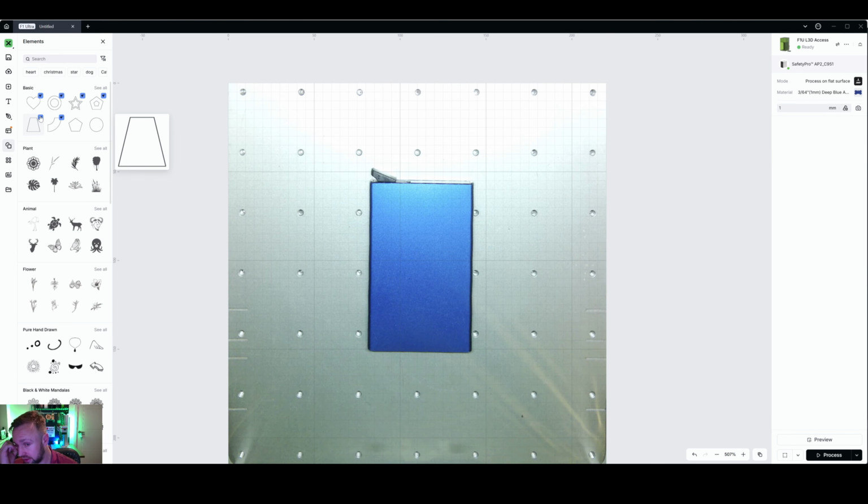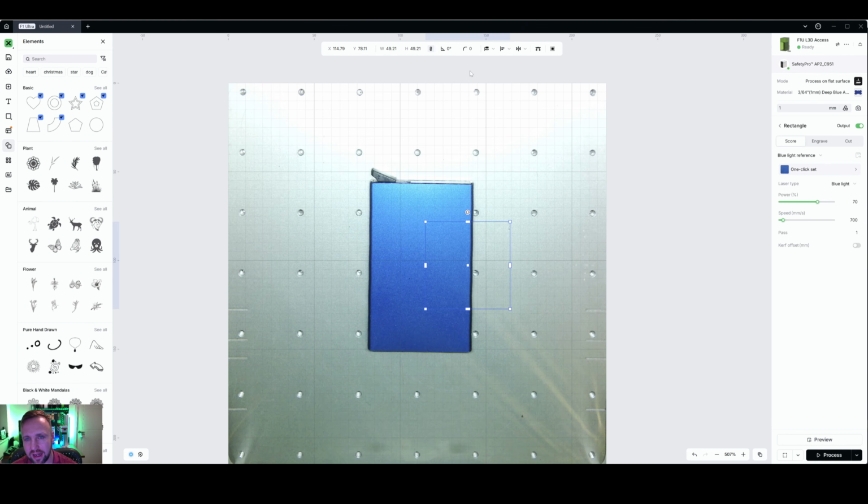So next thing I'm going to show you, so you now know how to import an image, you know how to edit an image, you know how to bring in vectors, bring in shapes. The next thing I'm going to show you is, let me just show you the offset tool because I went past that a minute ago. So let me draw our square here and there you go, you have it. I'll make it red so you can see it. So up there is this little hatch box. There is the offset command, and this is good if you ever want to invert an SVG, a vector image, to make the colors flip around on the dark surface. You can do inner and outer as you would normally have done, and there you go.